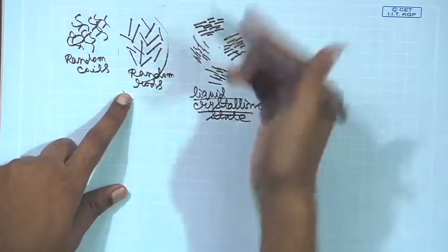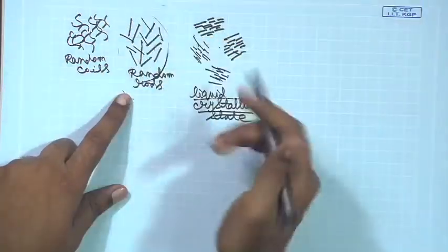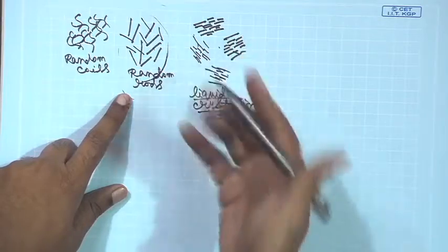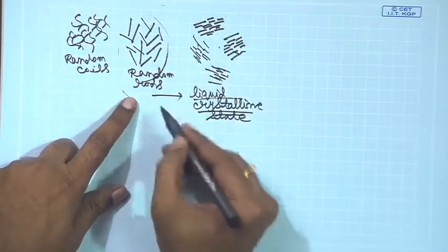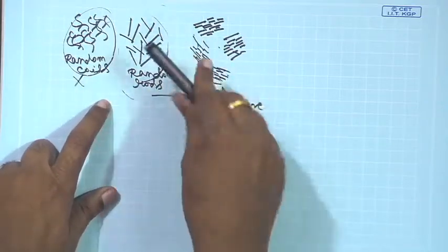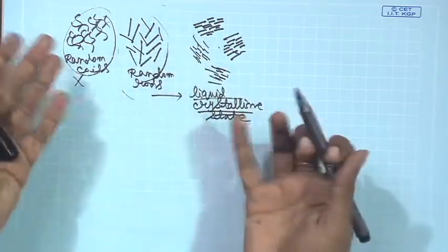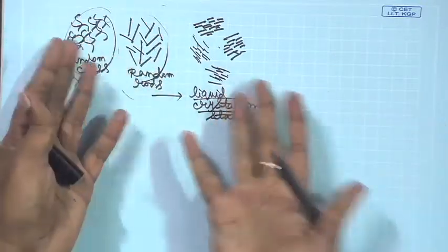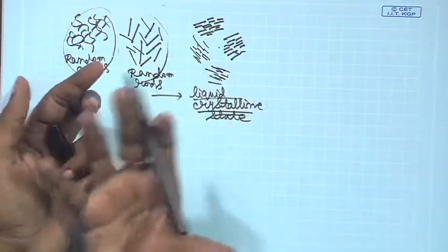Obviously, in all kinds of solvents, the same polymer when you dissolve it will not form this kind of state. So, it depends on which solvent you are using. That you have to standardize first. So, you have gone to higher concentration. This situation is existing here because we are talking about para-aramid fibers which are rigid rods. In the para position you have all the functionalities of the aromatic rings, and this is also rigid because you have a lot of aromatic units.